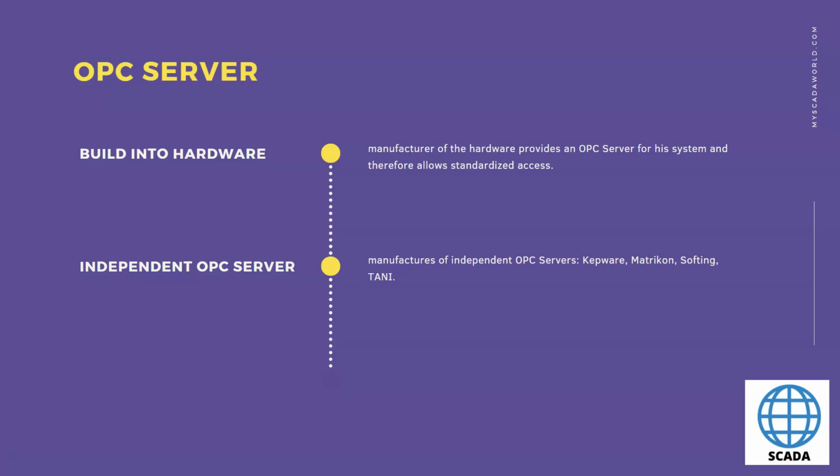We can use, for example, an independent OPC server like Kepware, and we can communicate with Siemens, Allen Bradley, GE Fanuc or any other, because Kepware is a high quality OPC server that gives us the possibility to communicate with, for example, 140 drivers inside.